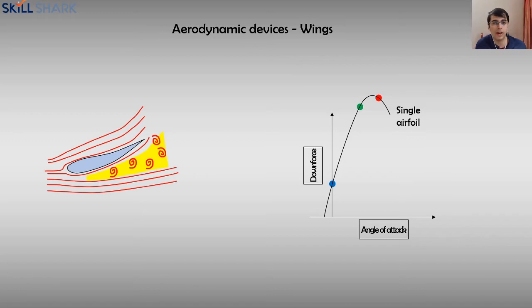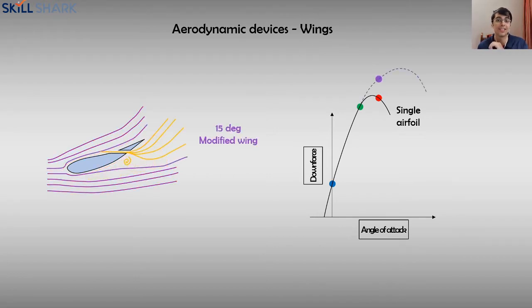And I mean, why don't we make a little slot there? That's a good way to re-energize the flow, right? Seems like the only logical way to send air over there. There you go. As soon as you create a slot and send air through that, you re-energize that zone, thereby decreasing the pressure. And so the air starts sticking together. Again, those cohesive forces become strong. You get more laminar flow as opposed to the turbulent flow that was present there. Of course, you still have small amounts of turbulence over here, but it's not as bad as what it was before.